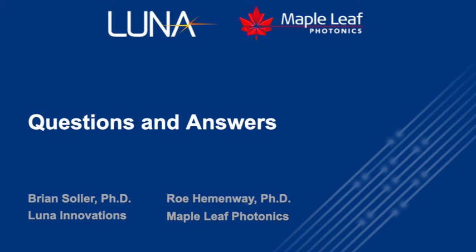For the OBR, it's a little different. It uses one polarization state only. So what we recommend there, if you really need to make sure you're launching a specific state, is you can marry that with one of our polarization controllers from our General Photonics product catalog, or you can include the addition of polarization maintaining fiber, and just make sure you're aligning to one of the modes of that fiber, and then you'll get, say, linear polarization out at the device.